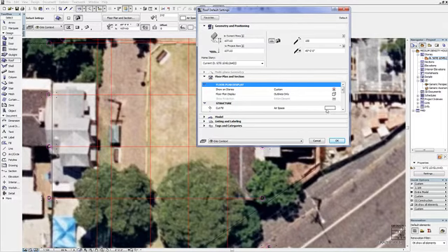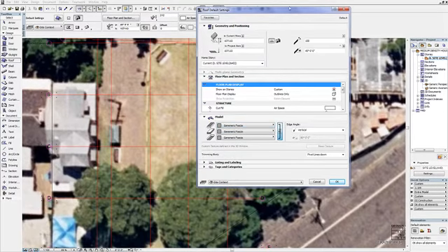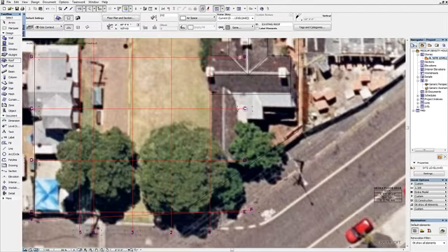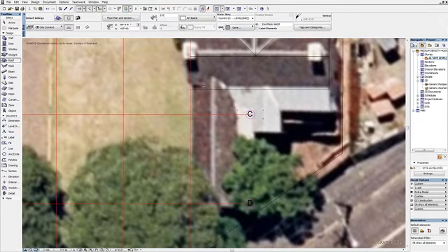All right, so we still want airspace. The model color we want to be consistent with the first roof that we just drew. We want it to be consistent with this color, so we're going to leave it as generic fascia. And then the site context is the correct layer. So we'll just press OK. Now, what we're going to do is draw the single plane. We're going to draw this one first.